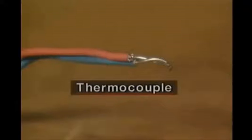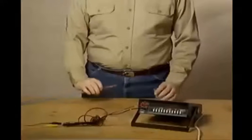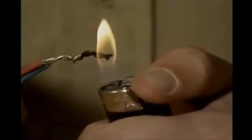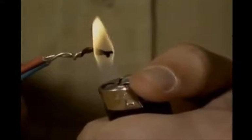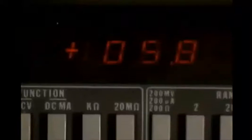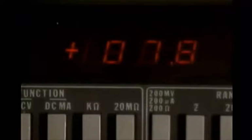Another source of electrical potential is heat. One device that uses this source is a thermocouple. A thermocouple basically consists of two dissimilar metals that are joined together. When heat is applied to a thermocouple, the electrons in the metals move in such a way that an electrical potential develops. If the thermocouple is connected as part of a complete flow path, current flow will result, as indicated on this meter. As more heat is applied, the electrical potential and the resulting current flow increase.